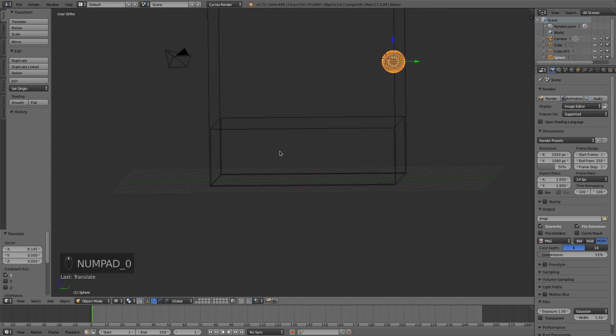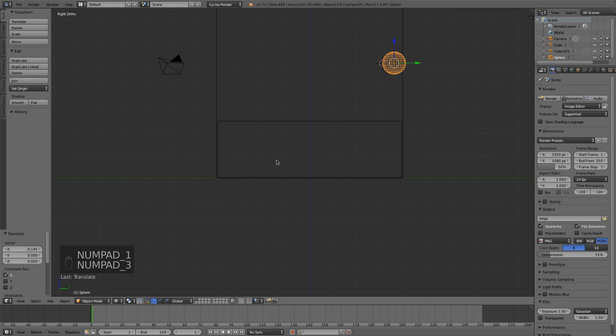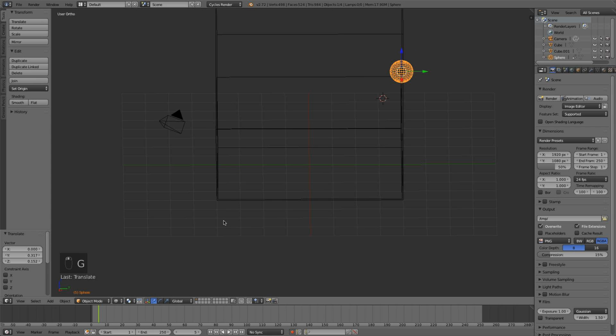And I'm just going to keyframe this now. So basically for the keyframing, let me choose automatic keyframe insertion because that's simplest. And we'll just have it start at frame 5. So grab it and let go of it so it puts a keyframe on it right there.